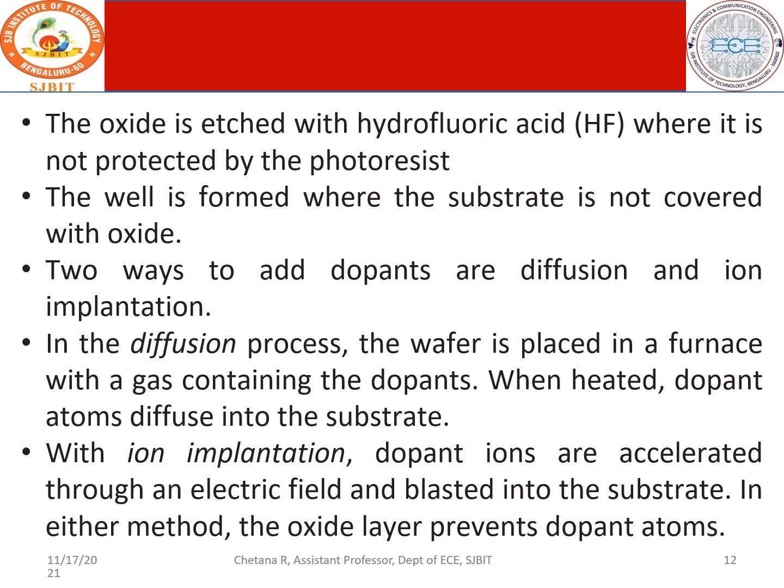But what is the procedure in ion implantation? Dopant ions are accelerated by an electric field. What is the type of dopant I want? It is the pentavalent element, phosphorus. The phosphorus ions are made to move with the help of an electric field and blasted into the substrate. So finally, N-type elements are made to move and sent into the substrate.